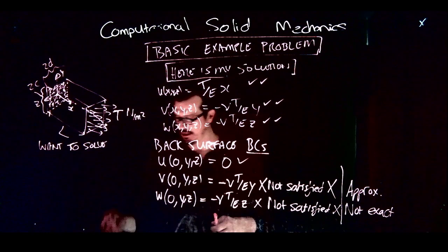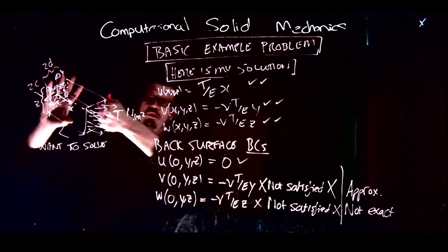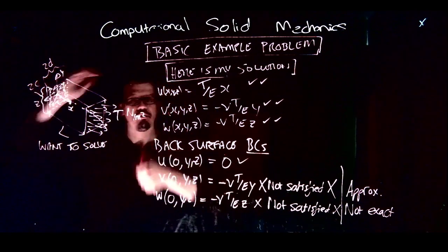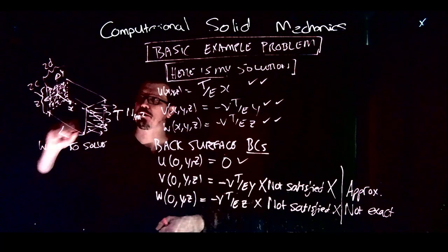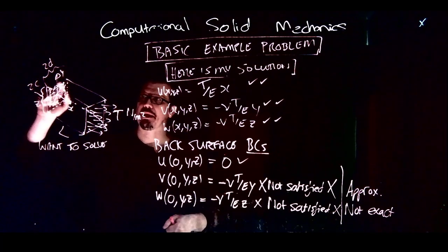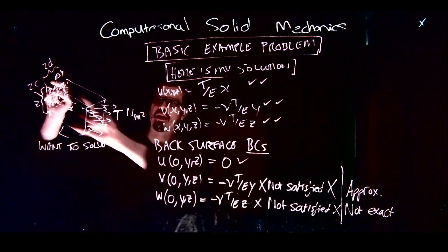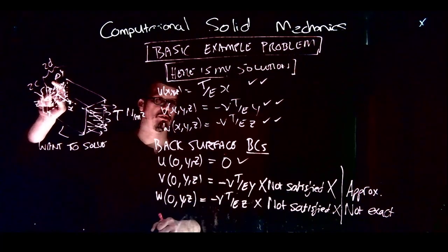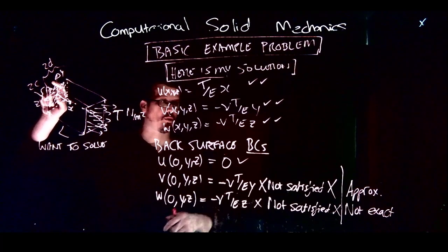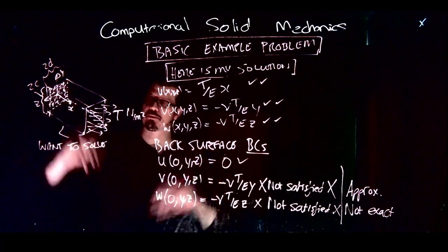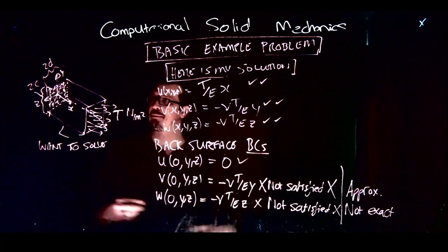And the reality, the sad part, is if you were to pull on this structure, and if you were to imagine where stresses could evolve that could be high, if I were to clamp that thing at the back plate, there might be some high stresses developing there that I'm not capturing at all. I'm only capturing the axial component of the stress with this solution. And so that's why it's also good to rather say, let's approximate solutions in general numerically. That's what the finite element method is going to be about.